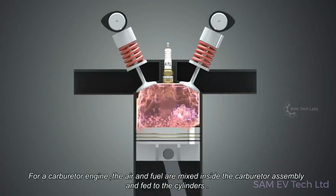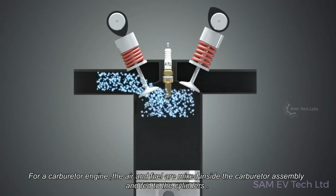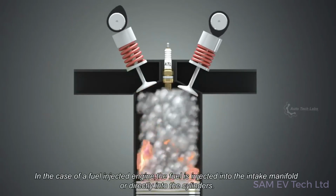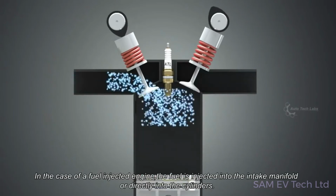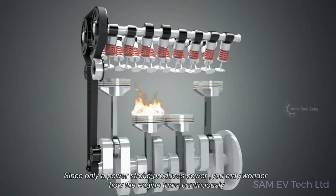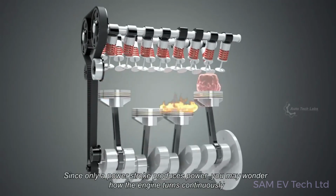For a carburetor engine, the air and fuel are mixed inside the carburetor assembly, and fed to the cylinders. In the case of a fuel-injected engine, the fuel is injected into the intake manifold, or directly into the cylinders. Since only a power stroke produces power, you may wonder how the engine turns continuously.